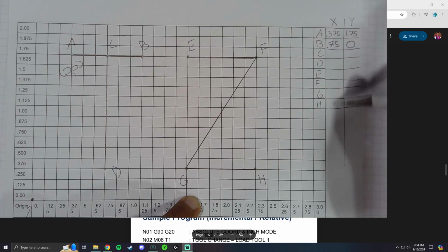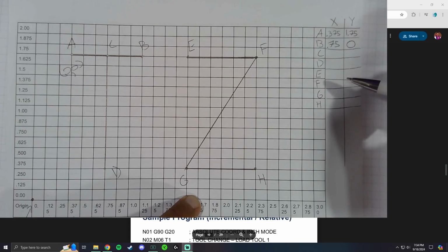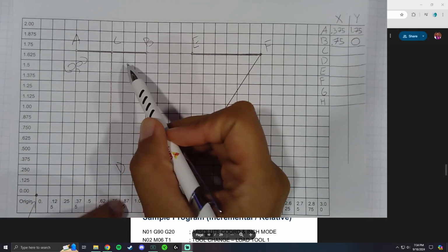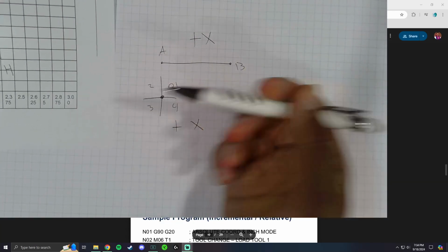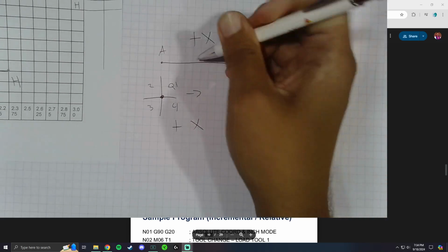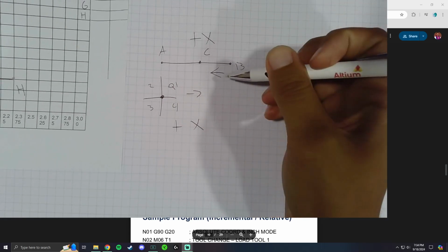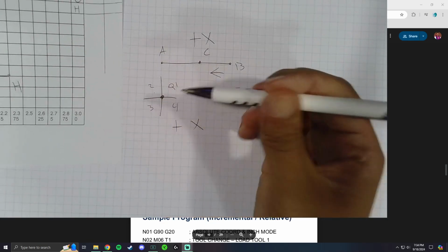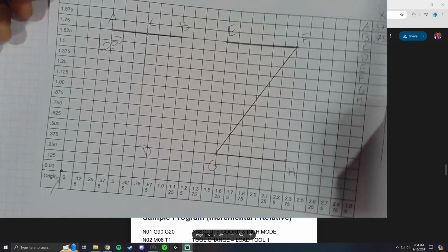Now, this is going to be a requirement for this first practice, your X and Y's, with the paper of your 2 letters and your X and Y's, so make sure you do that. Now, going back to C, C is also going to be an X movement, but like I just talked about before, you're moving from your 0, 0 again, going to the left. So from B, going back to the middle to C, I'm going this way to the left, which is going to be a negative X, because if I'm on my origin, going to quadrant 2, you have a negative X direction.